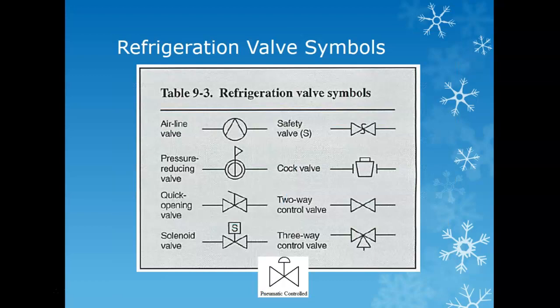So these are some different valve symbols. Again, these are specialty valves. So you have the airline valve, the safety valve, which everything always has safety valves, right? What do you not want to do with those safety valves? Don't ever want to override or damage them. Safety and pressure relief valves are there for a reason.